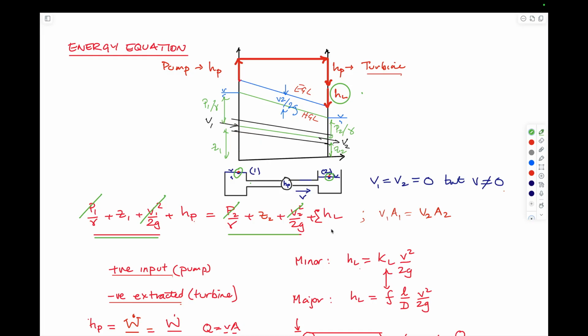The velocities that are used in the head loss, which are here, are average velocities within the conduit. And so the fact that you'd have 0 velocities at the upstream, this velocity would be in the linking pipe that you're flowing along. If the velocities are 0, yes, okay, that's making the same point here. Upstream and downstream velocities may be 0, but the average velocity in the pipe might not be, and you have to be able to account for that.